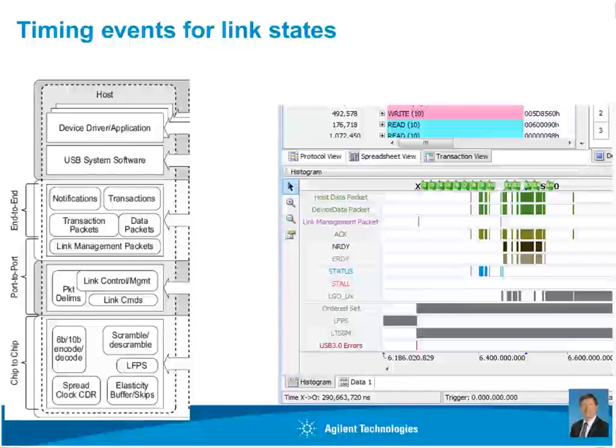And in that transition, there were some errors on the link, then link management traffic that occurred. Then there was another significant period of time of just doing all the training sequence, the ordered sets, of getting all the receivers synchronized. Critical time for some of the scope operations and seeing that. But once you get past that, then the data starts flowing. And that data starts comprising all of your reads and writes.